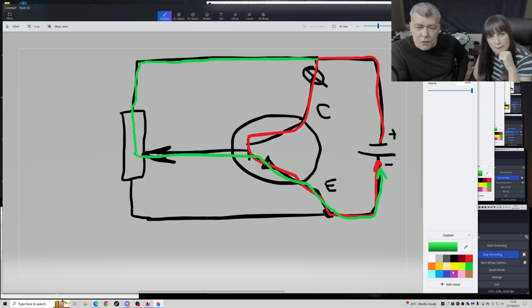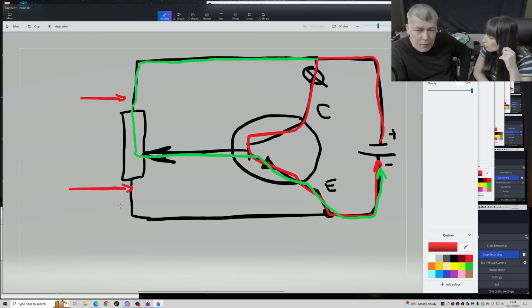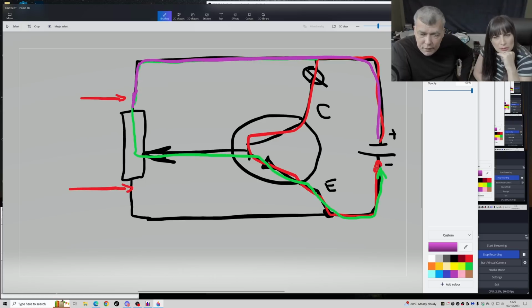What is the voltage across this resistor? What will the voltage be if you check it with the multimeter from here to here? It will be 0.7. How? You have this track, yeah? This track is coming straight from your battery. You can see it? So what voltage will be there? What voltage do you have on the battery? Exactly. So I'll have the battery voltage. That means if I have a resistor here, I will have a current flow, from the plus to minus.